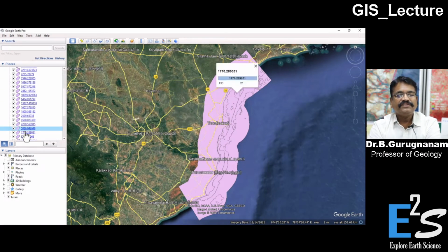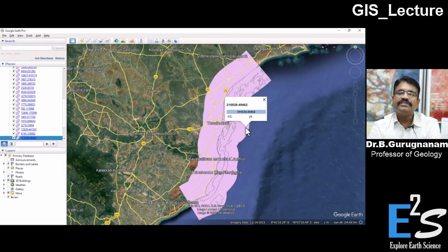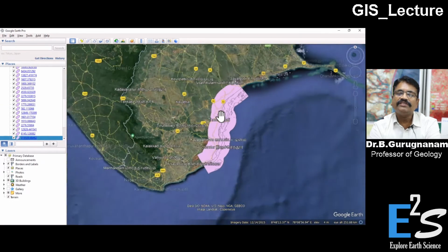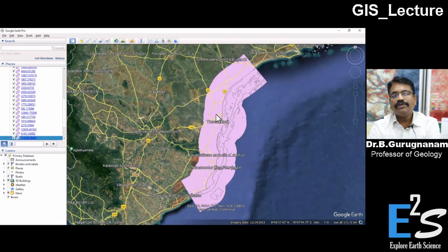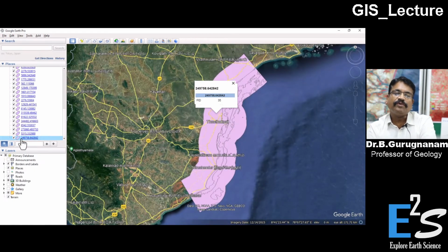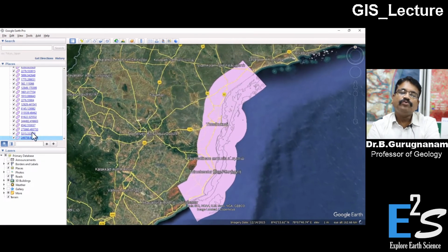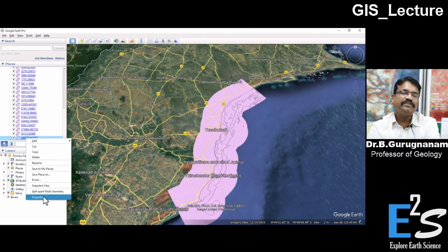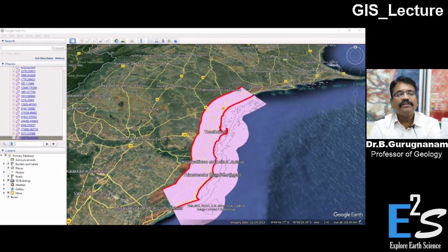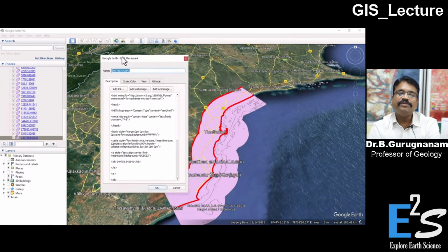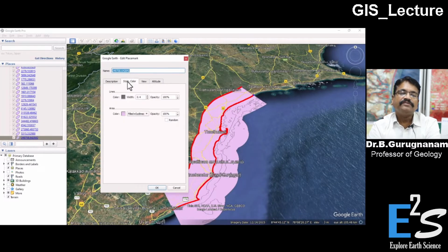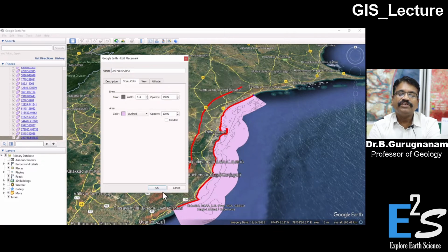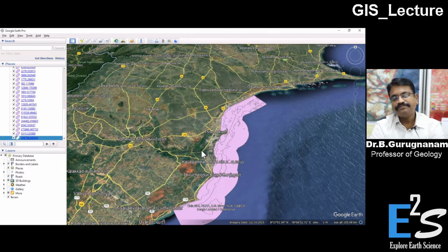And this has a lot of applications that you just check. You can also move your cursor and click over a particular polygon. It will show you the ID of the particular polygon. And once you know the ID of the particular polygon, you uncheck it and automatically you will be able to see the bottom transparent. You style the color, you make it none. Just give the outline and then check the bottom.